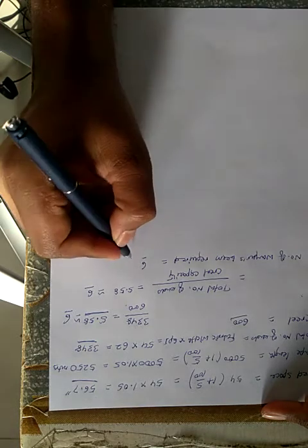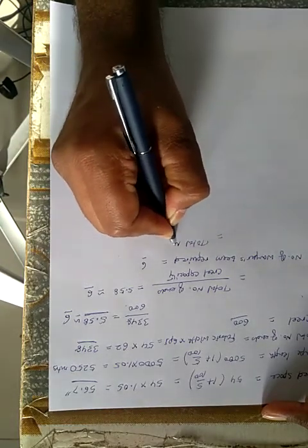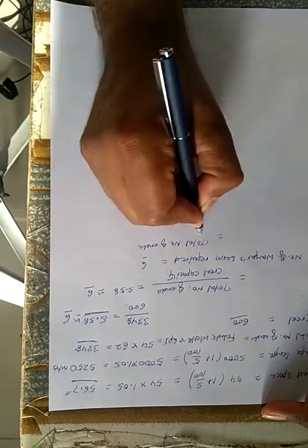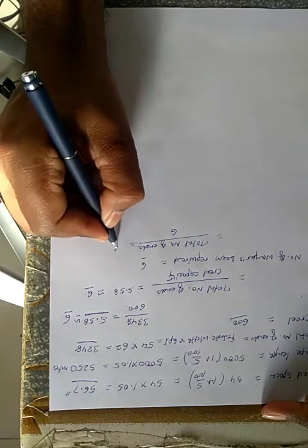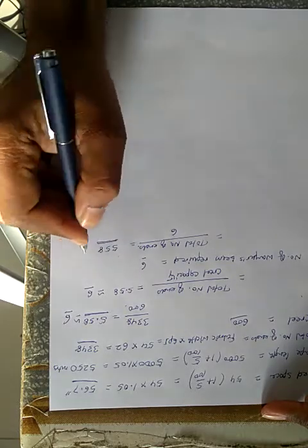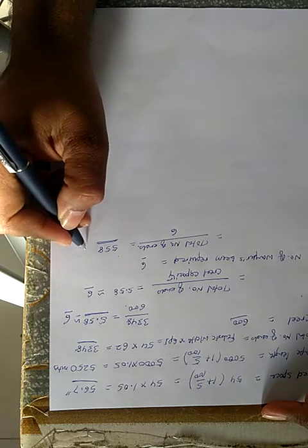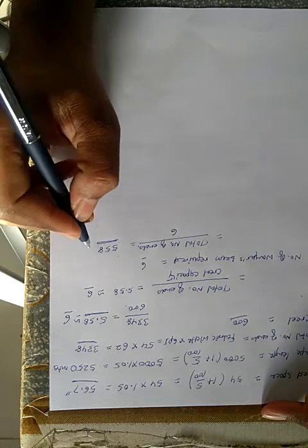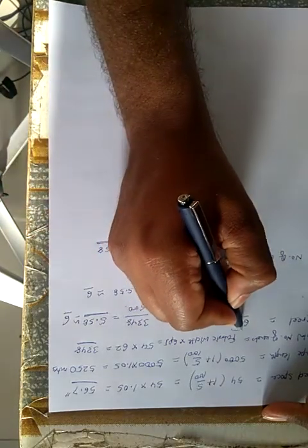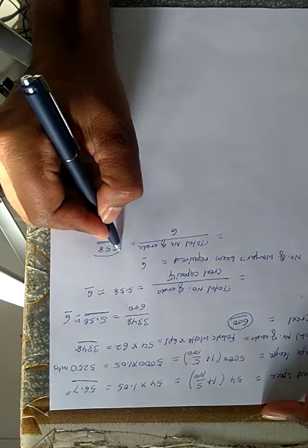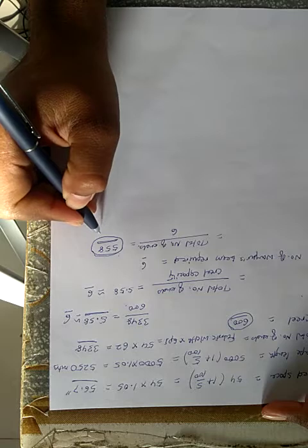Now we will divide 3348 by 6. Total number of ends divided by 6 gives us 558. This is the number of ends we require in one warper's beam. So here we will not use our maximum creel capacity, we will use 558 as our creel capacity to produce a single warper's beam.